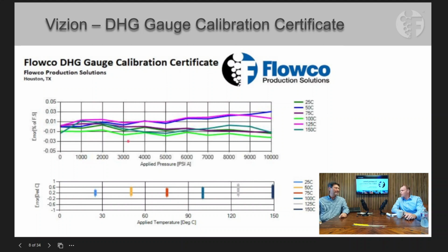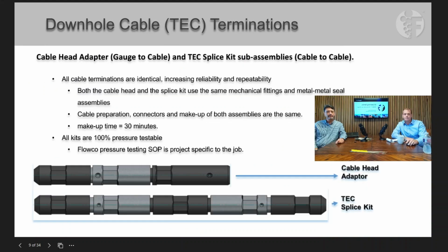And so that's important, right? Is that temperatures aren't going to vary much from reservoir to reservoir or well to well, but I guess from reservoir to reservoir, if you look at an Eagle Ford well, they're going to be closer to that 150 C. Whereas you look at, say, a Permian Basin well, I don't know what the number is, let's just say 75 C, right? But it's going to be significantly lower in temperature. And so looking at this calibration scale, understanding your reservoir temperature, your environmental temperature, is important to know, right? Yeah. Okay. That's good to hear.